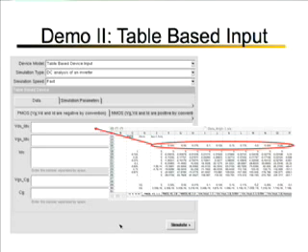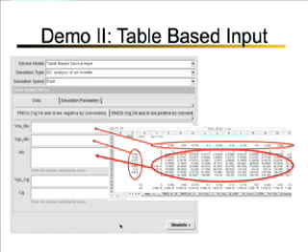So what I'll do is I'll provide the VD values in this blank space in the VD column. We will provide the VG values and the 2D matrix of current in this blank space. It's as simple as just putting these numbers in, and then similarly we do the same thing for the capacitors. And this is done for the PMOS, and similarly if you go to the next tab, you can do the same thing for the NMOS. And finally, you have to choose the right simulation parameters like VDD and parasitics and things like that, so that the entire simulation can be done.